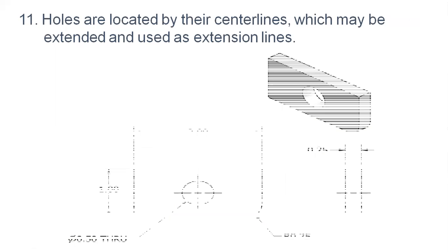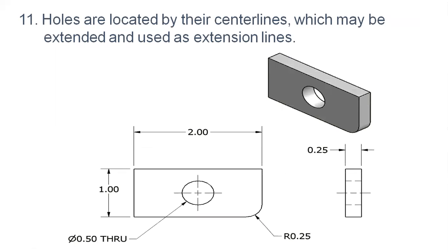Then holes are located by their center lines, which may be extended and used as extension lines.